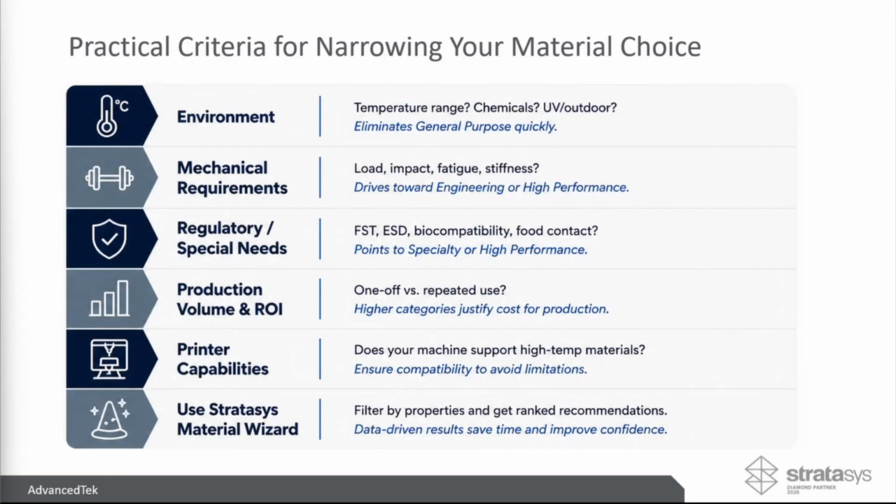What are your mechanical requirements? What's the load going to be on it? Is it going to see any impact or fatigue from repeated use, or does it need higher stiffness? Probably going to drive you towards your engineering or high performance. Is there any regulatory or special needs like FST, ESD requirements for electronics? Is it going to be coming into contact with food, or does biocompatibility play a key role in it? Probably going to point to your specialty or high performance materials.